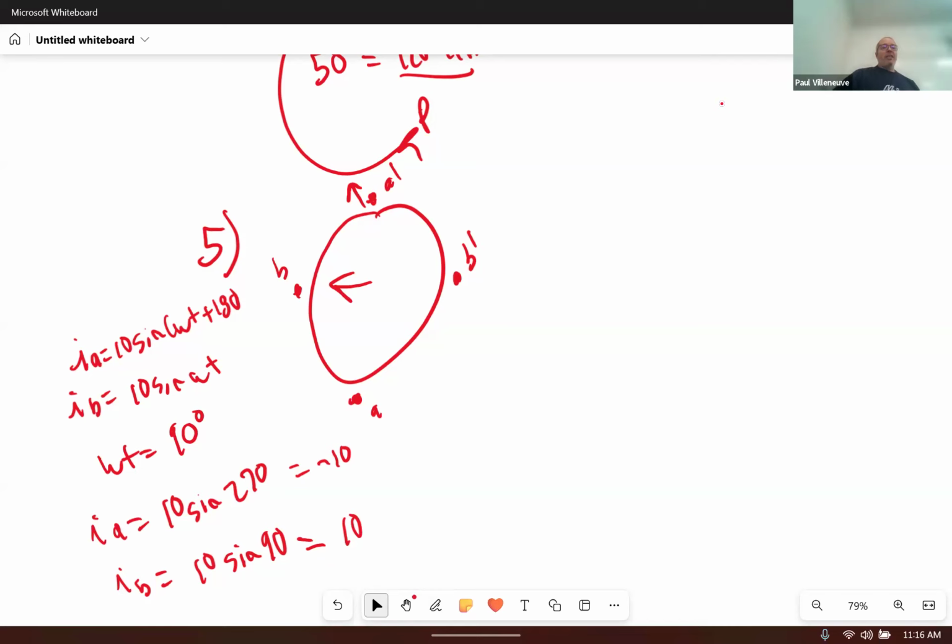Now I run my current B. Same thing. Since these are the peak and it says the peak magnetic flux density is 5 times, B sub A should be equal to 5 times the peak current. And B sub B is equal to 5, again, times the peak current here. You just have to put the angles together and add them up. All you needed to do.